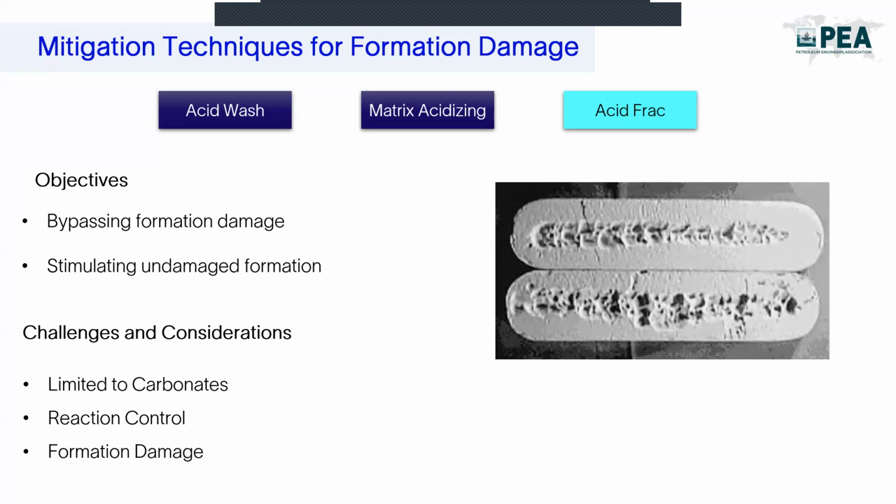So the acid travels down the fracture and is transported to the fracture walls, resulting in dissolution and performing the etching phenomena into the rock itself. So if the etching is non-uniform, it's differential, then the fracture may close and reduce the conductivity.